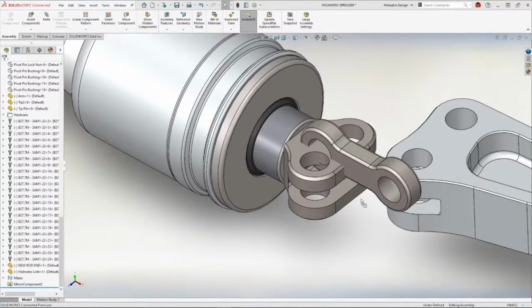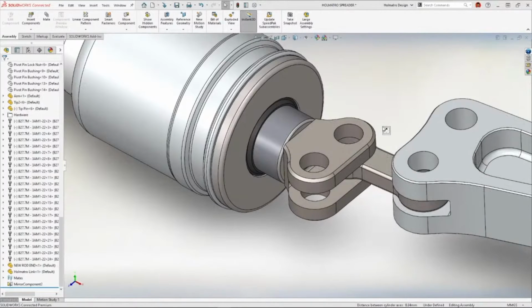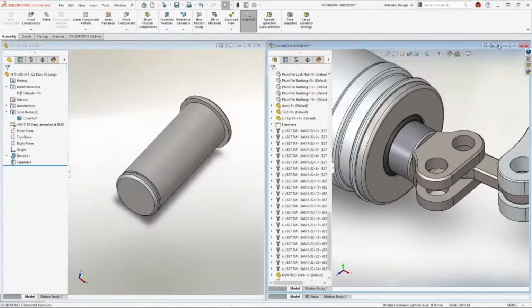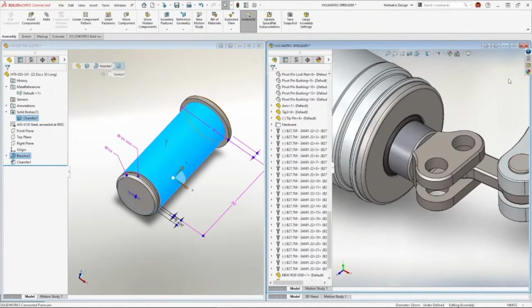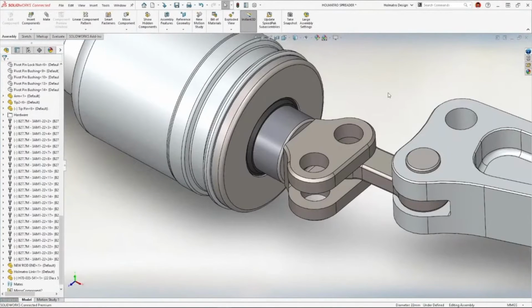It's just a matter of adding the mates like we did before. So we're going to fast forward through this one a little bit as well. But even so, there's still a pin. And because this isn't a full design demo, we have one in the other window. But watch as we drag and drop between all of these different holes. So we can really just choose which hole we want to drop this pin in, and it is going to add the mate automatically.